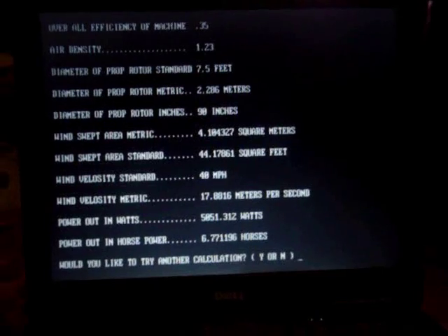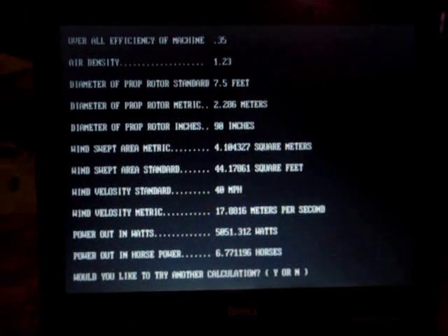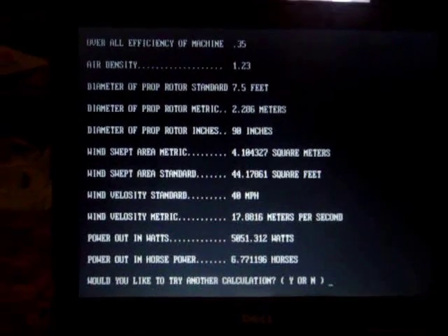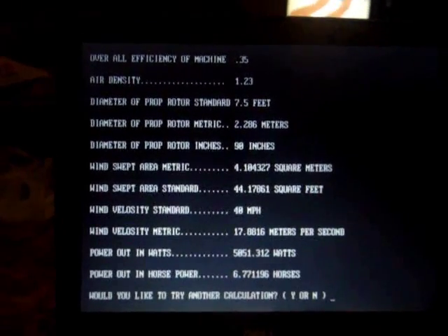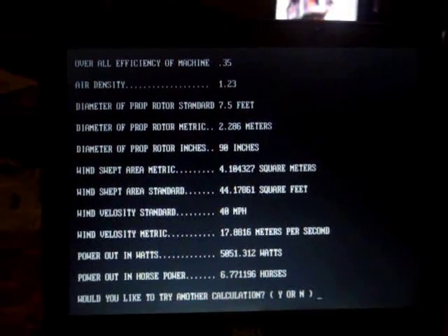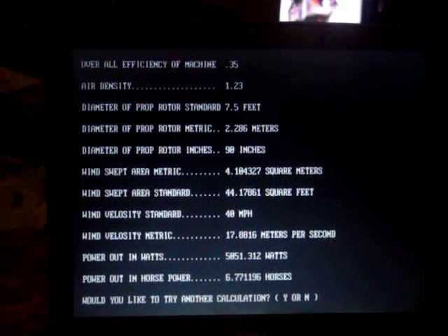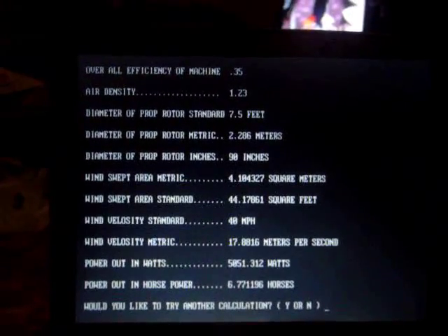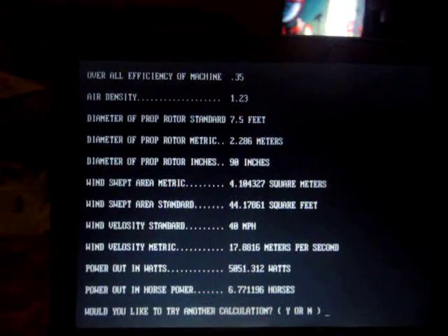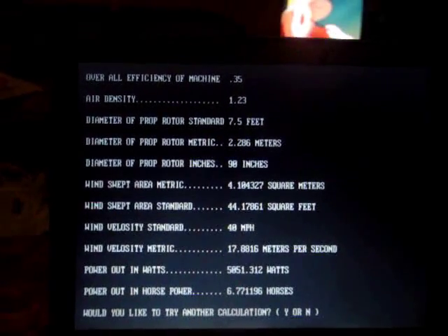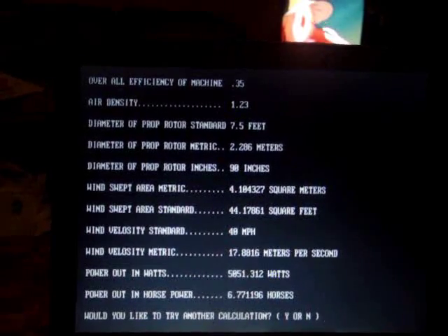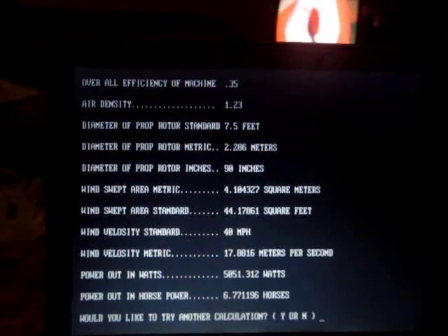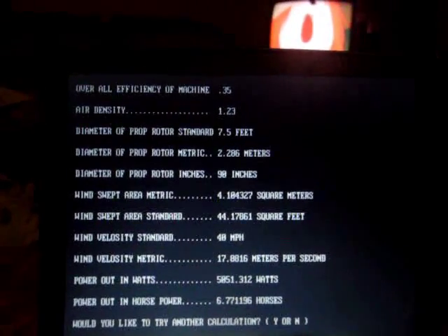So, when somebody says they've got a 1.5 kilowatt wind turbine, well, maybe the wires can handle it, but does it take a 36 mile an hour wind to get it there? And if the wind goes down by half, you've only got 1/8 the power. How many days of the year do you have 35 mile an hour winds? And if you go down to our normal winds, well, we've cut it down by another 1/8. So that'd be 1/64 of the power.